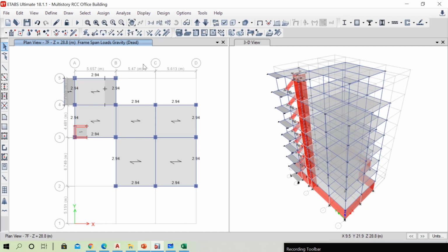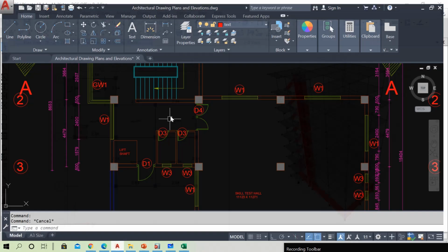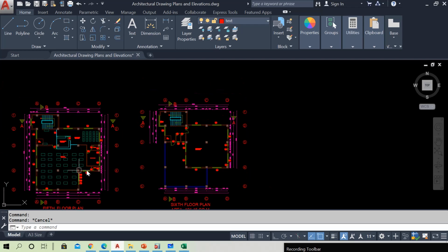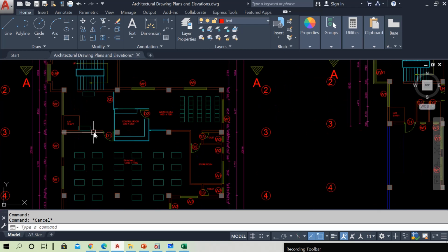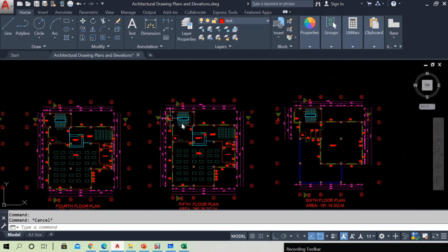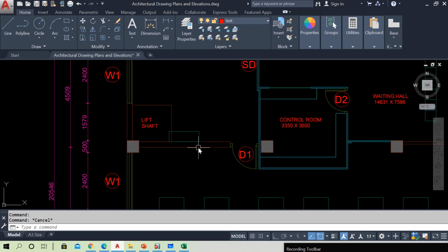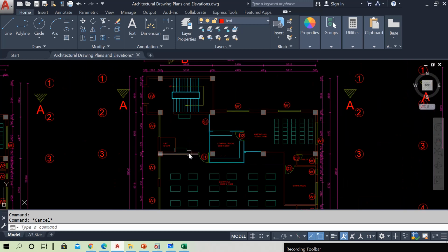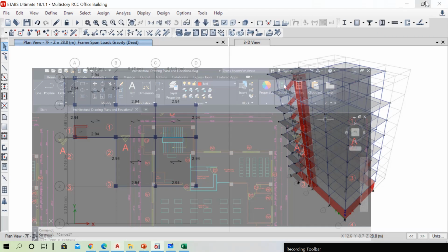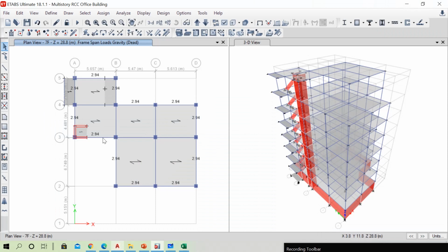So now I think the application of masonry wall load is complete because there aren't other masonry walls inside our building. There are some partition walls. Okay, there is one wall here along this grid where we have, let's suppose, a masonry wall with opening but of half brick thick only. So what we will do is, we don't need to select this beam on this floor level. Let's go below.